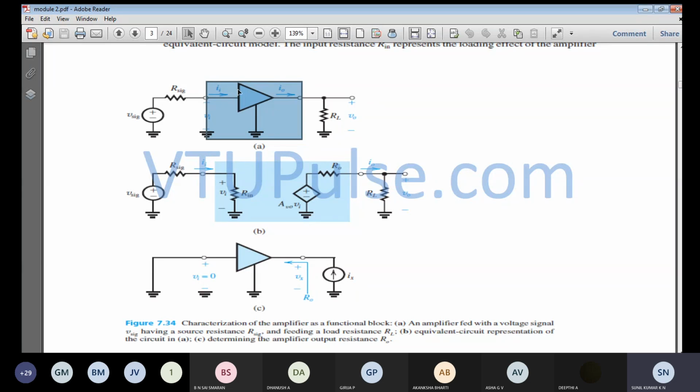So this functional diagram has been removed, and in place of that we write the voltage amplifier over here. Why am I calling it a voltage amplifier? Because we have voltage at the input and voltage at the output, and we give the voltage amplification for this amplifier, because it is a MOSFET amplifier. In this MOSFET, the input will normally be the gate to source voltage. In any MOSFET amplifier the input is in terms of voltage, and you get the output across the drain to source. The gain, that means the ratio of output voltage to input voltage, is the voltage amplification.